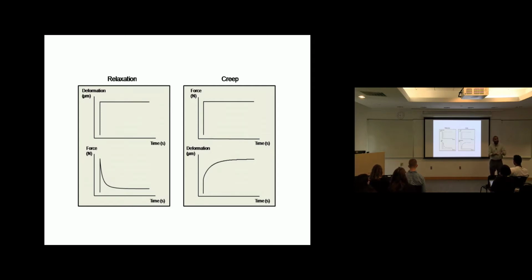Now I'm deforming it and giving them the chance to break and reform both. But as you apply a force, the equilibrium moves more towards the broken state. That means it gets softer, but it takes time to get there. And that's the time scale of relaxation you're seeing. Bringing in newer crosslinks is a new concept. We'll have to go back to that, that's plasticity.